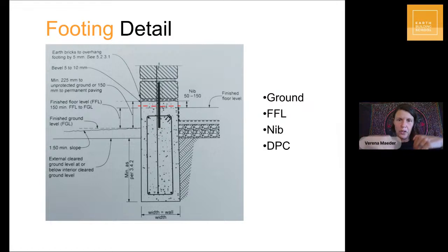They transfer the load of the building into the ground and make sure that things like ground settlement, slumping, and so forth don't happen. So the stability really starts in the ground and really can make or break your building. And it's particularly important with the heavier construction methods, like even the low density adobe is still a lot of weight. The other thing that the foundation does is it raises the building out of the moisture of the ground.